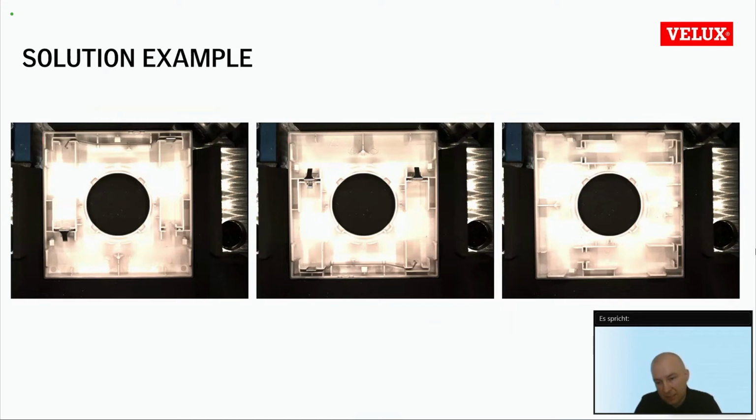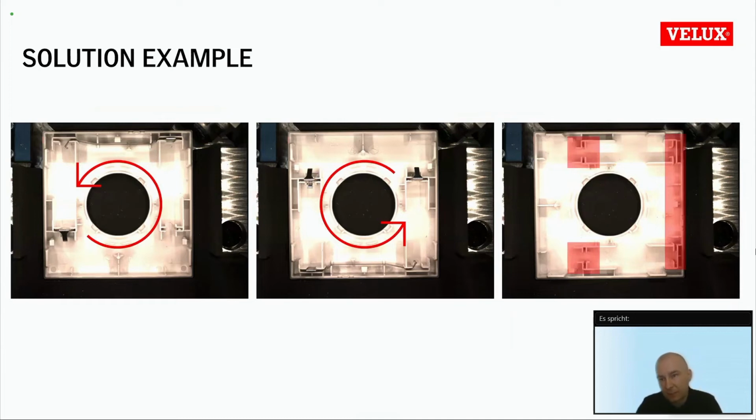This is a plastic cover for a remote control for our windows at Velux. And this has to be picked from a cardboard box and fit into the automatic assembly line. The orientation in the box can vary in all four directions. So we need to first figure out the orientation, and we also need to check if the battery clips are mounted by the manufacturer of these subcomponents.